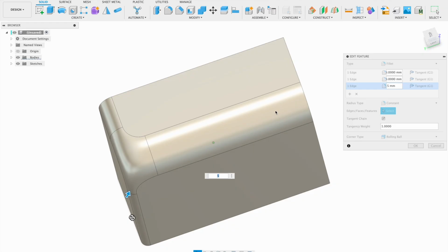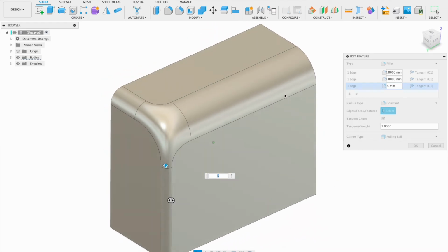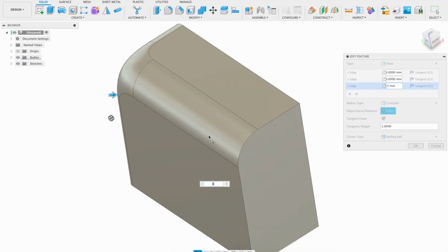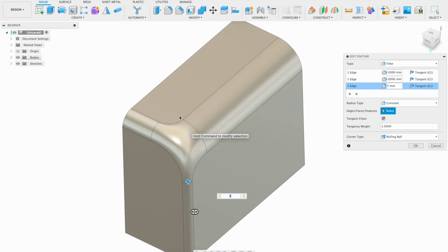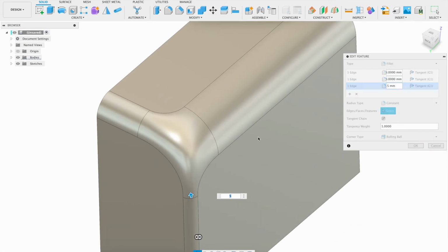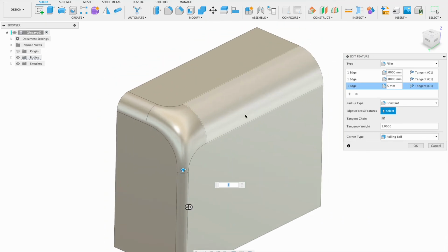See, you have different fillets intersecting at the corner, and these fillets are designed in such a way by Fusion that they interact with each other without a problem. Now, there is a box next to the fillets, as you can see. This controls the tangency.